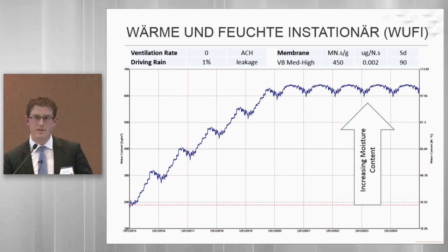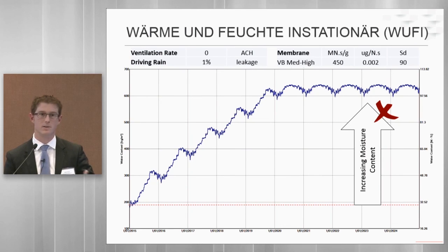So what you might get out of this software or simulation package is something that looks like this. And this is a poorly designed construction system, and I can tell this because I can see the moisture content increasing over the first 4 to 5 years, and it gets to a level that's completely unsustainable, that's going to produce mould and timber rot, and the system's likely to have a very short lifespan.